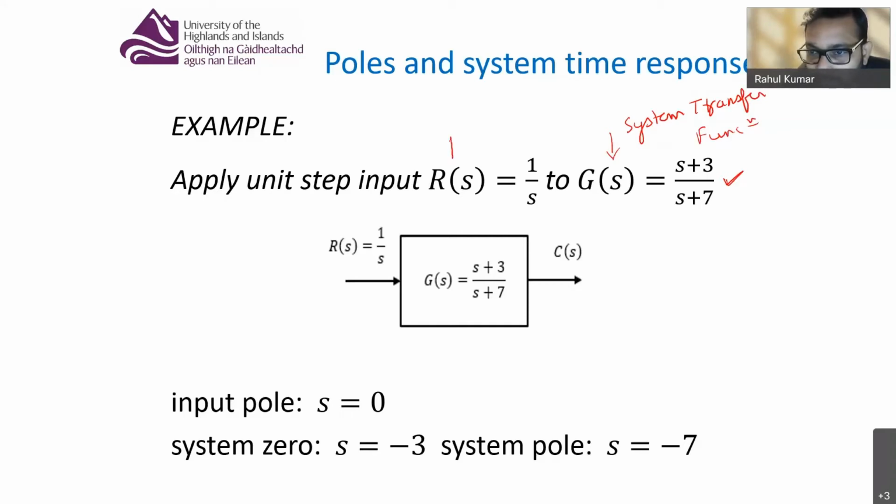And I am applying a unit step input, that's my input, R(s). For a step input in the s domain, if you remember, it is 1/s. So I have taken this transfer function and I am applying the step input.